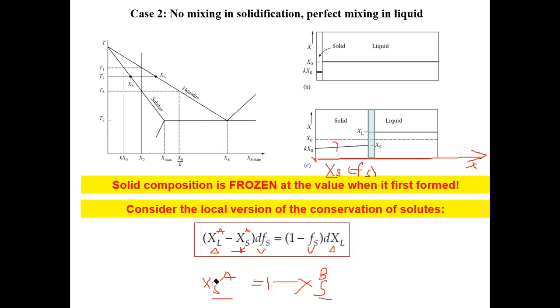So what do we have? What is our setup for the phase diagram? Why did we initially introduce the assumption that both the liquidus and solidus are straight lines? What is the consequence if these two are straight lines? You can use y equals mx plus b, and two points will give you the slope. Yes, and more directly, if both of them are straight lines, we have a relation which is true for all compositions. We have a relation between the liquid and solid composition for all of the temperatures within T1 to T3, during the entire solidification process.